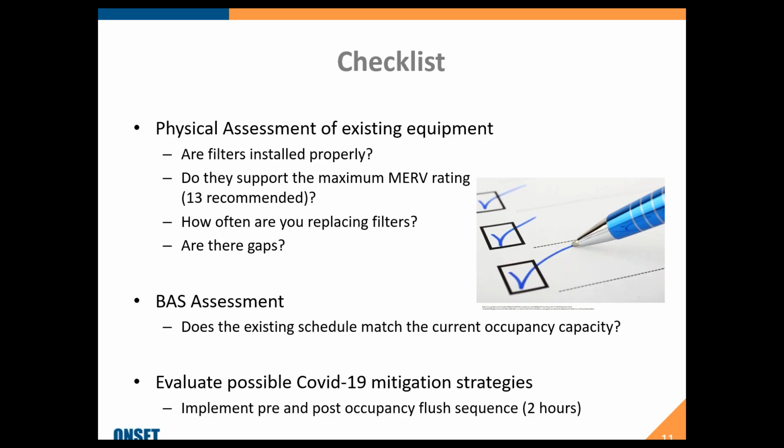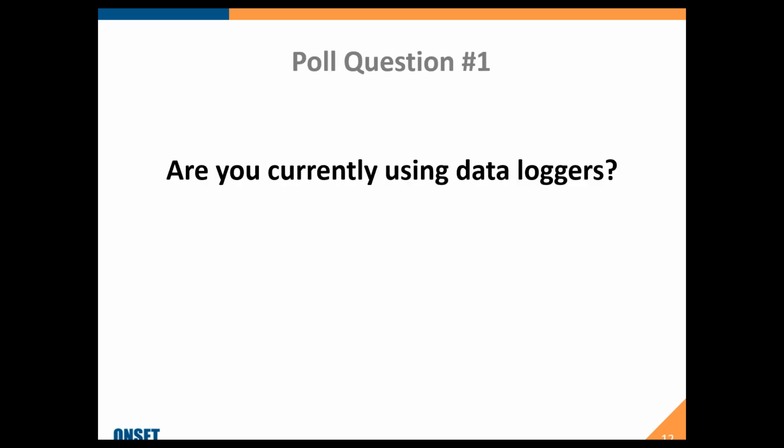And at the end of the day, you're going to find that this is where our equipment also comes into place, to verify that a building automation system might be working correctly, using portable data loggers, which ASHRAE does recommend, or even just handheld instruments, to be able to make sure that those areas are working the way that they're supposed to be working. If you want to hit the next slide.